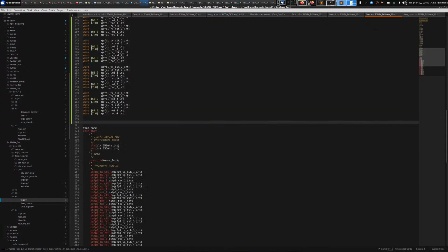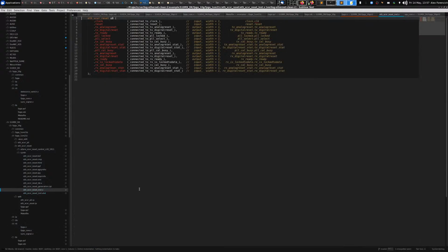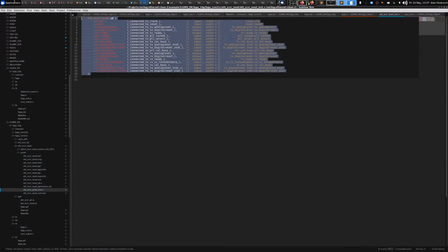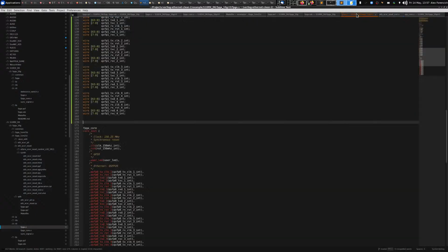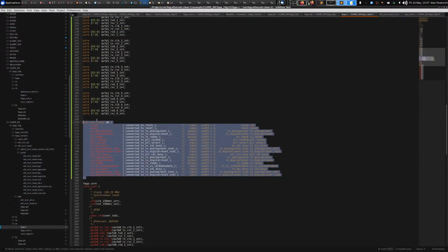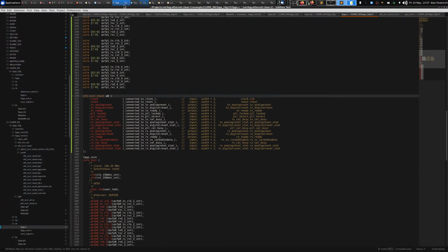All right, so while that's running, I'm going to go ahead and start plopping down some of these modules. When it generates the IP, it generates some associated Verilog files. So this one has the instantiation template for the reset module, for example. I'm going to go ahead and put this in. Still working. Okay, so for this one, this needs just a free-running clock. So I'm going to use a 100 megahertz clock and 100 megahertz reset for that.